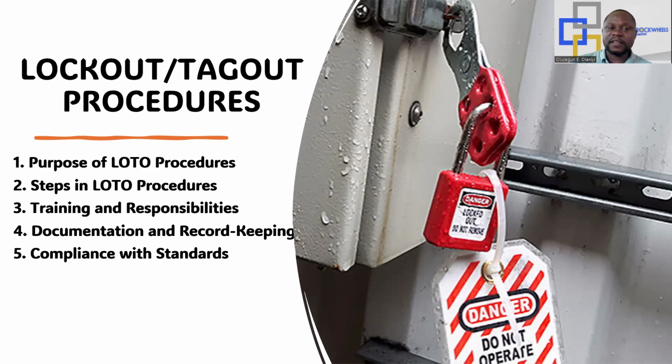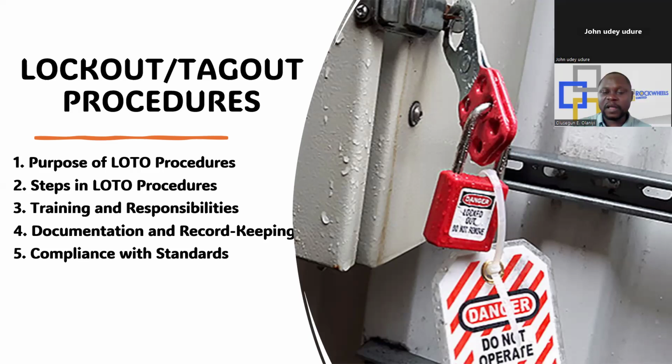Then the next step is verification. Test the equipment or the machinery to verify that it is really de-energized. Then you ensure no residual energy. When we talk of residual energy, we are talking of some tiny energy that is actually stored in your device. This could cause a serious disability or fatality in the industry. I will come back to you, John, but let me conclude with this.